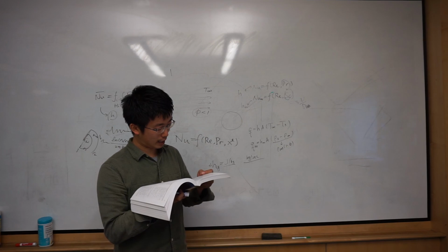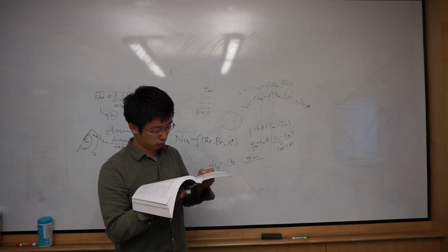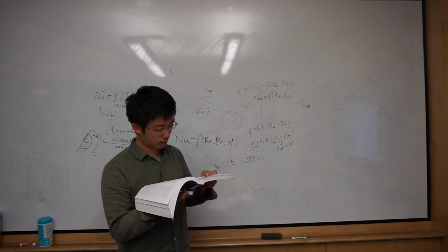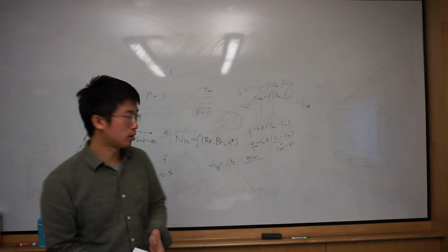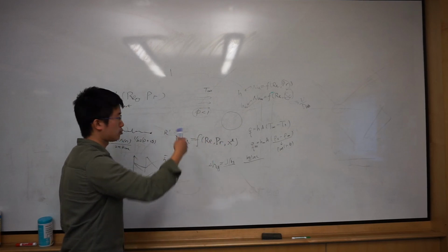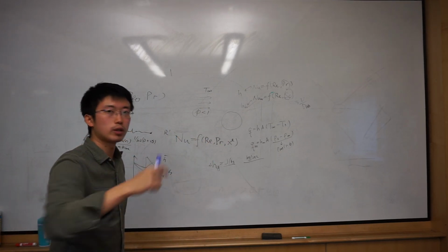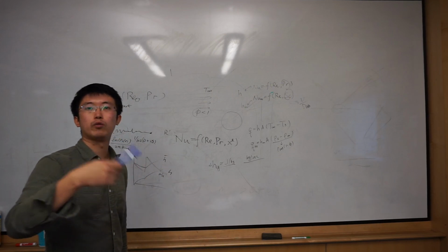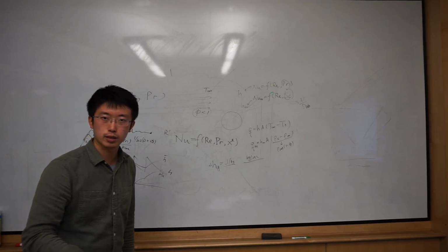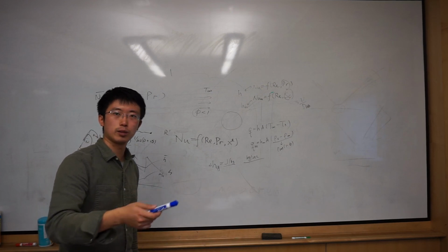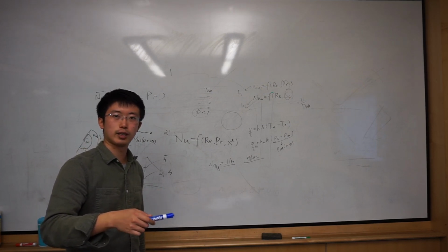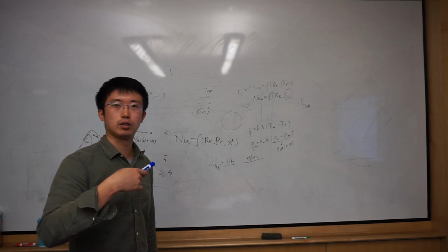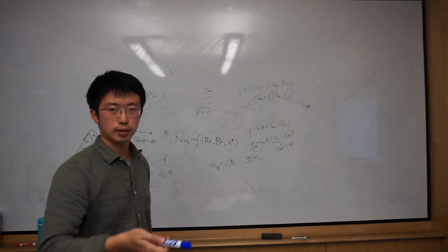So how is the variation of the local maximum and minimum? Now we basically have more than one possible transition zone, right? First question, where does it turn to turbulence? Second, when it turns to turbulence, the heat transfer is actually enhanced locally. But when it separates, the heat transfer deteriorates.